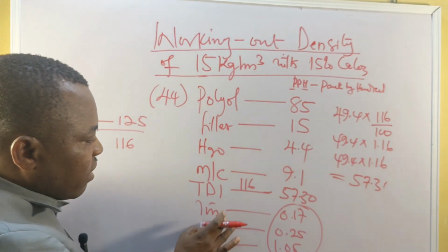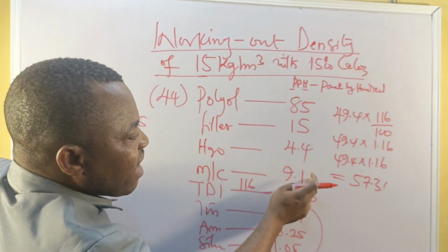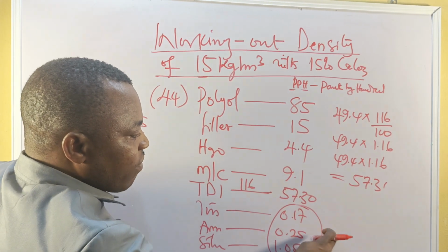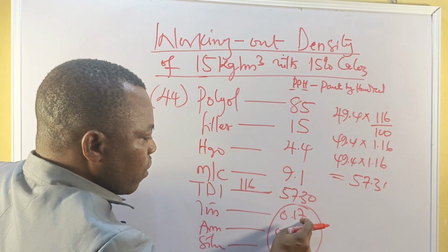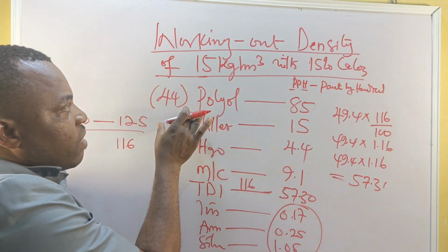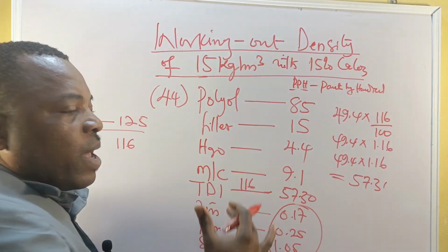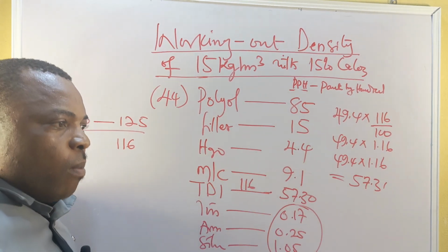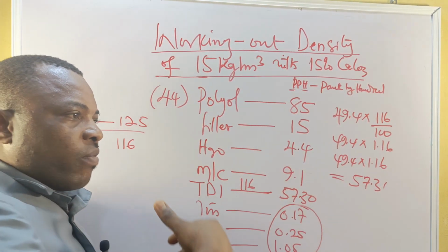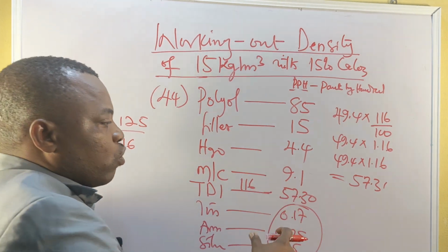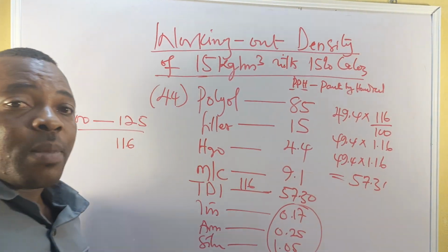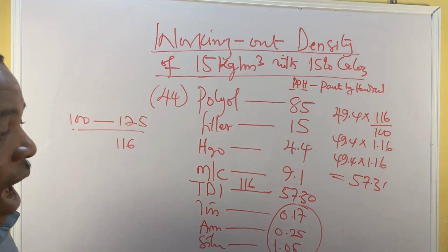The secret of choosing tin catalyst is that as you are increasing your methylene chloride, because it attacks stannous, you have to shoot this one up, I mean the stannous. Then the amine: because it is a low density, the blowing agent is a bit higher, so the foam tends to rise quick. So in that case, some of the amine increases the rising, so you don't need to pour more amine. But the function of amine, apart from influencing other chemicals, can also make it dry faster and cure.